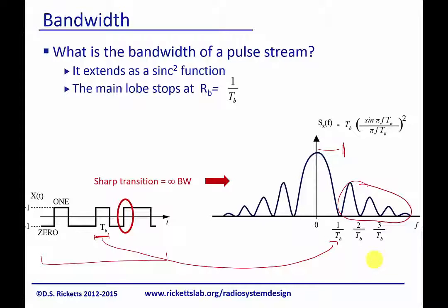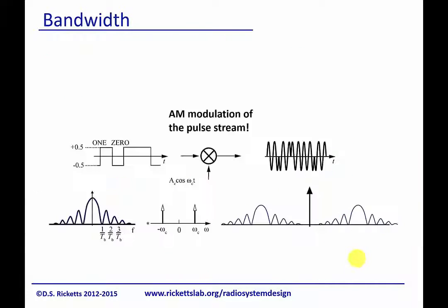And if you think about the olden days with FM radio, the reason you couldn't put more stations on the dial was because you needed a certain amount of space between them because their bandwidth was a certain size. If each one of those started transmitting a digital signal, they would overlap over all of them nearby. So for digital modulation, we've got to figure out some way to fix this modulation bandwidth creep.